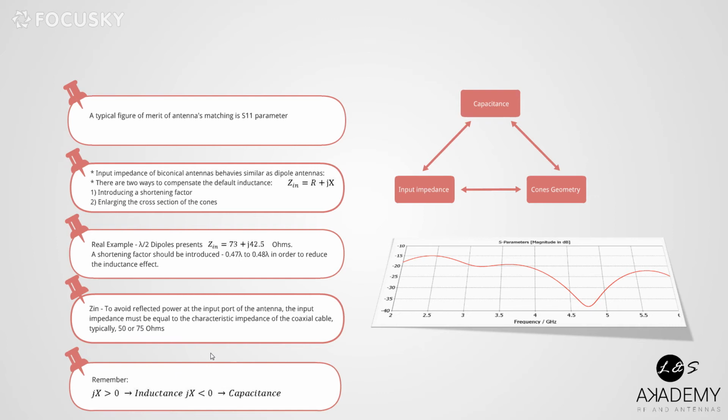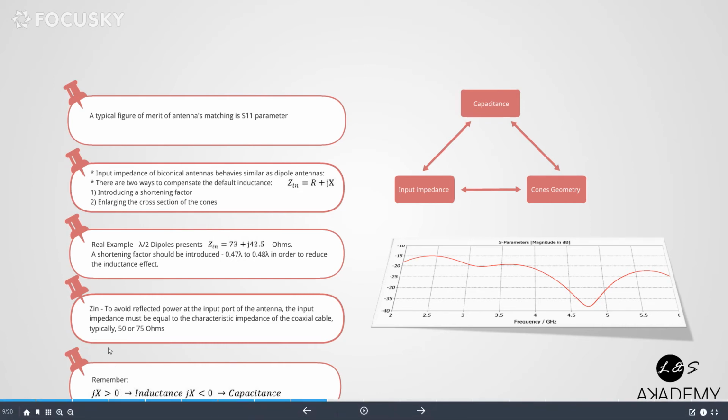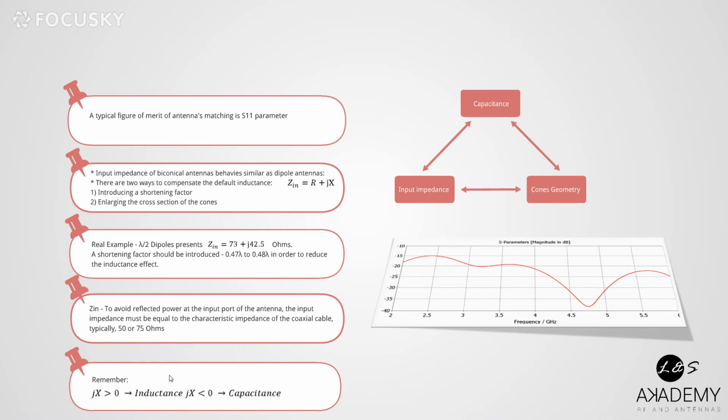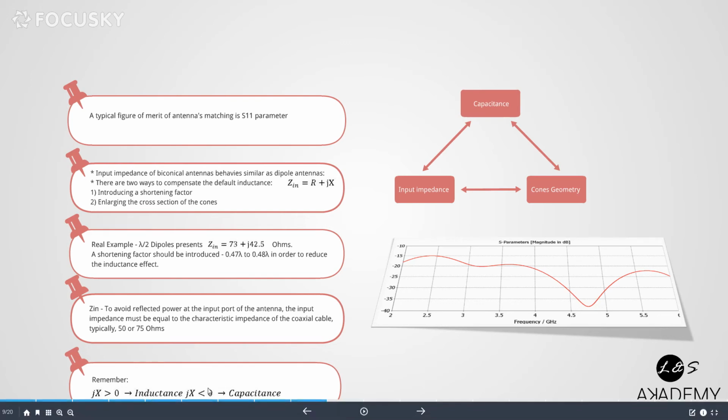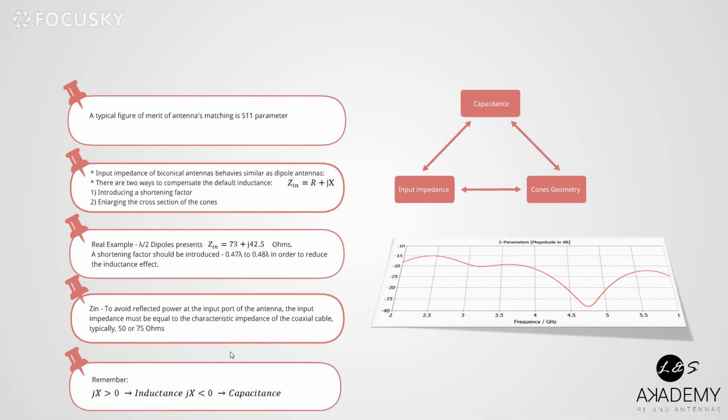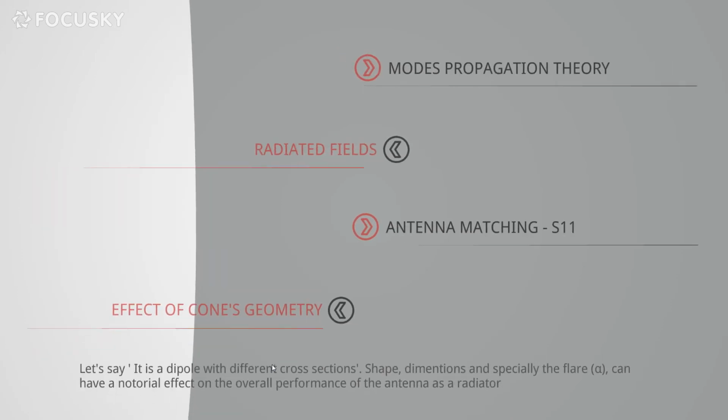So this is all regarding S11 impedance matching. Remember, this is important: a positive sign means inductance effect, and a negative sign means capacitance effect. Okay, so let's move on to the effect of cone geometry.